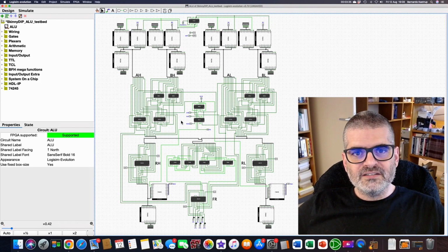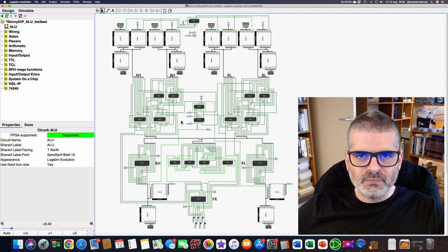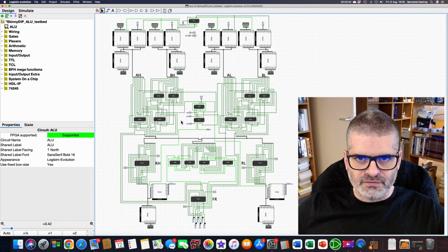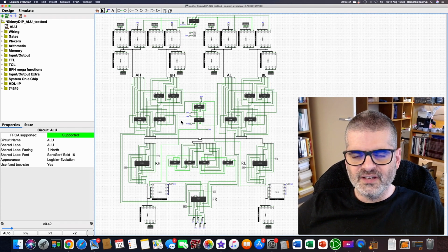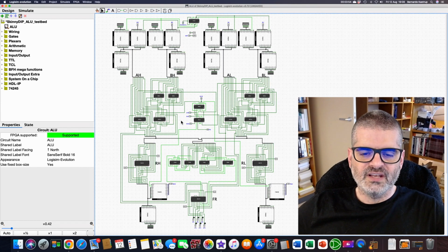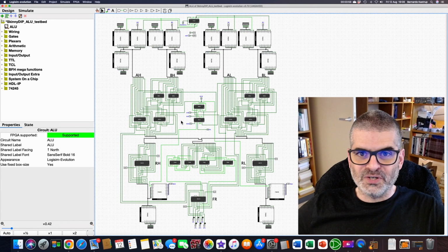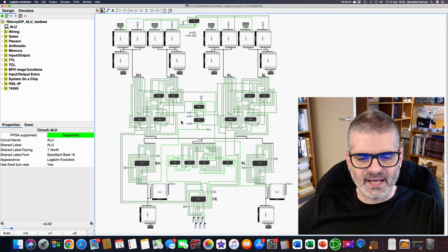There is only one circumstance in which designers still today will specify a circuit at the level of individual gates. Not in schematics. We will always do that in a hardware description language like VHDL or Verilog, which allows us to specify a circuit at the level of individual gates by writing commands, because it's much less error prone than trying to draw schematics.